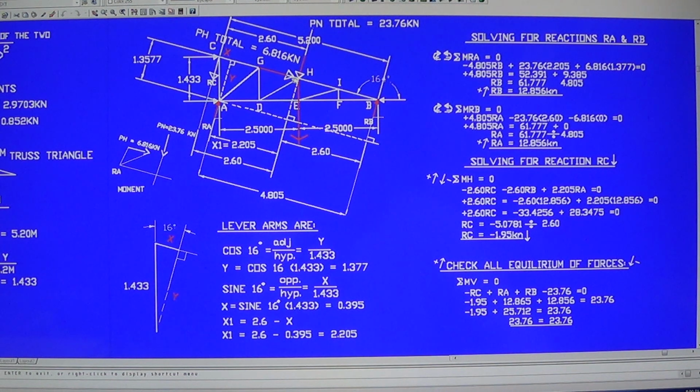So the lever arm for PN is not this one here, no. You gotta look for the 90 degrees intersection line there: the perpendicular distance from the line of action to the axis of rotation, and same thing with the horizontal load. That follows the definition of moment. The lever arm for PH right here is not this one, it's not 90 degrees. The 90 degrees is right here.